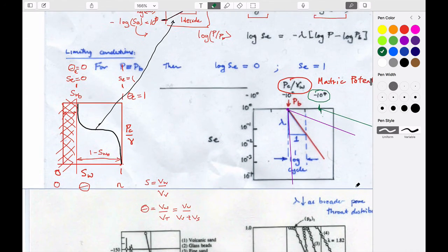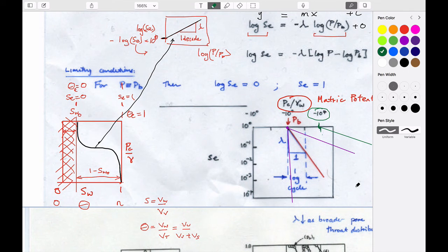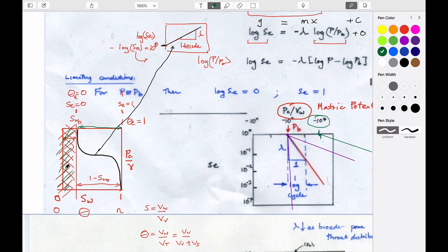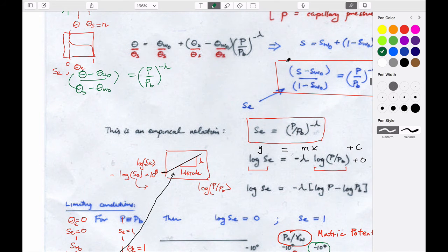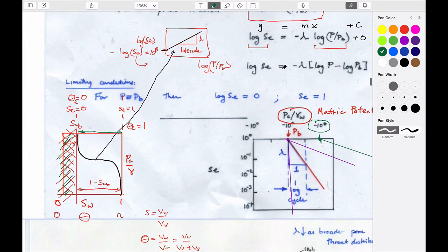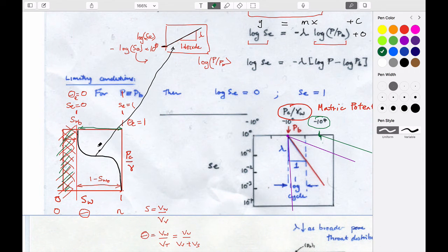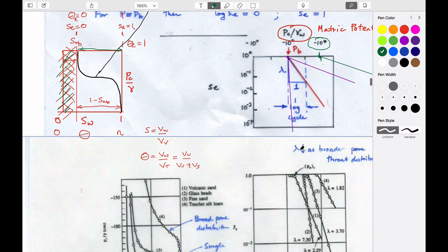So we'd like to be able to rationalize using this effective saturation, which is the length along this axis, to be able to define the change in saturation that just leaves out this portion for the irreducible saturation of water. So it's just changed the scaling slightly by using this particular term here. So we're using this term here to be able to represent an effective saturation. What we might like to do is be able to define these curves either looking like this or looking like this, just from knowing what our material is, not actually measuring it, because they're actually quite difficult things to measure.